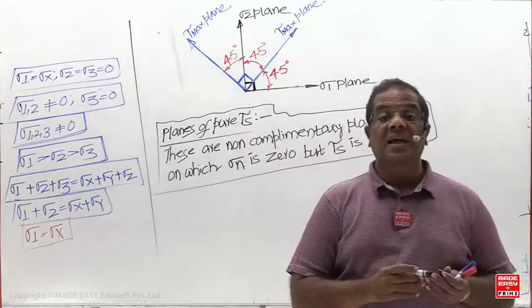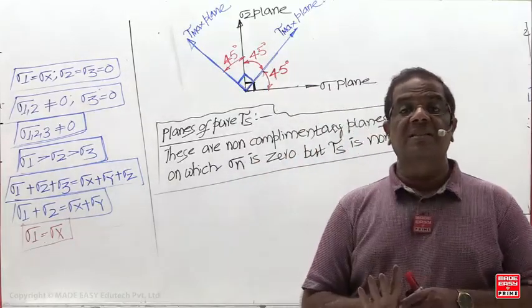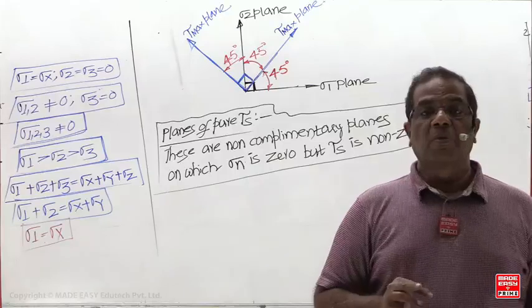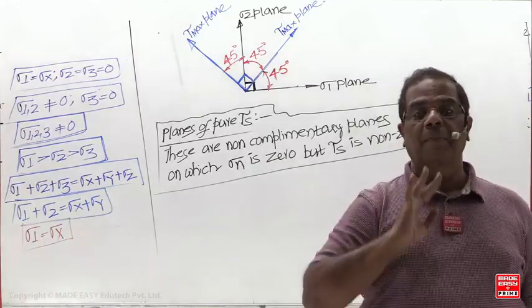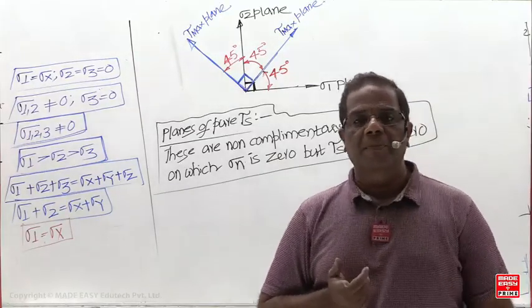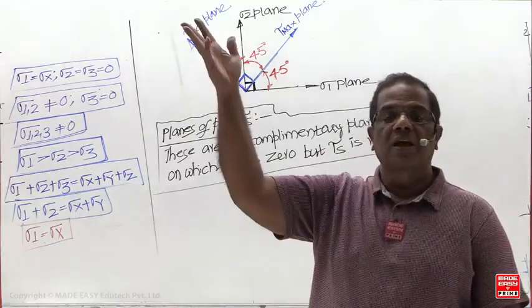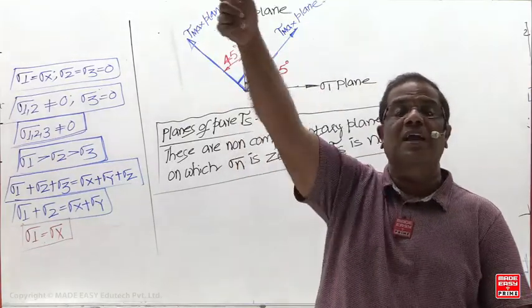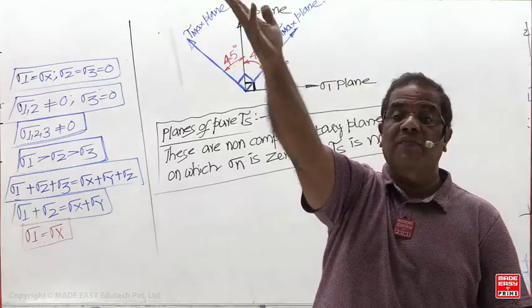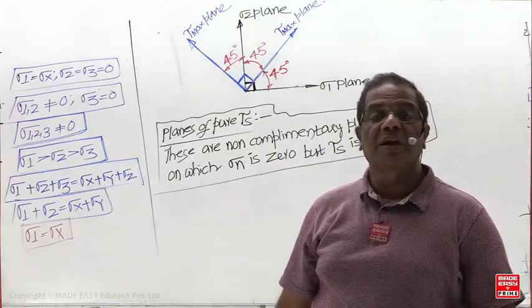So there is no practical significance of this plane. Generally these planes are not discussed. Most textbooks discuss only the principal plane and tau max plane. Why do you need the principal plane, on which normal stress is maximum? Because if you know the maximum normal stress plane, we can locate the fracture plane for brittle material. And why do you need the tau max plane?